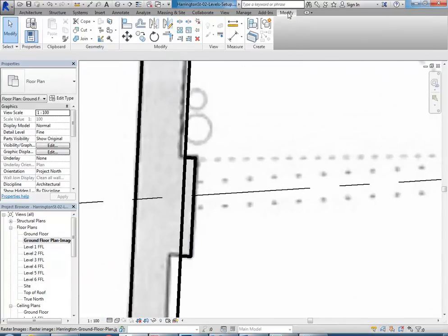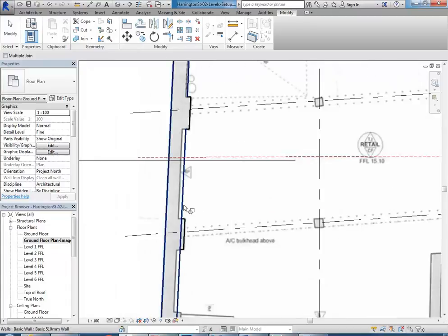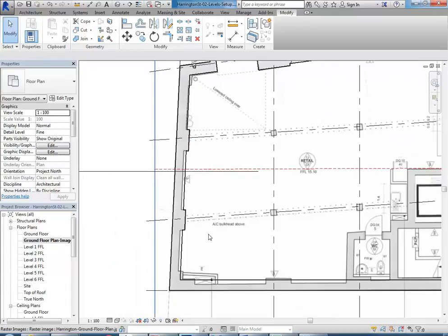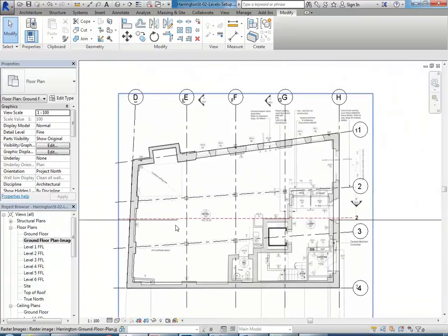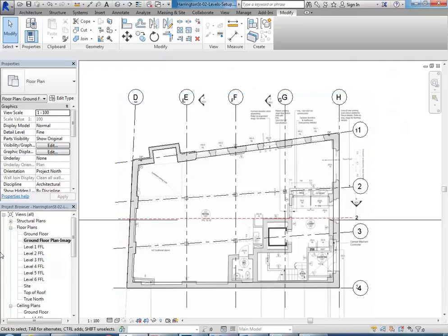Just use the join tool on the modify tab. You have the join button and you can then choose those two walls and they'll read as one. So that's a good way of doing changes in thickness as you have with things like piers. Okay, so you should be able to just go ahead and do most of the walls like that.